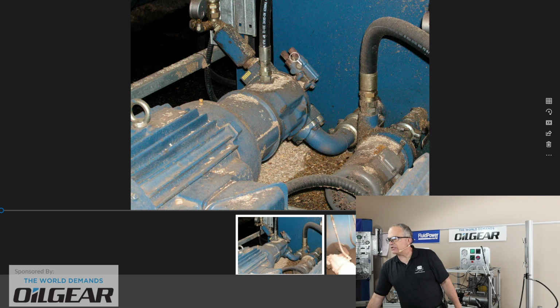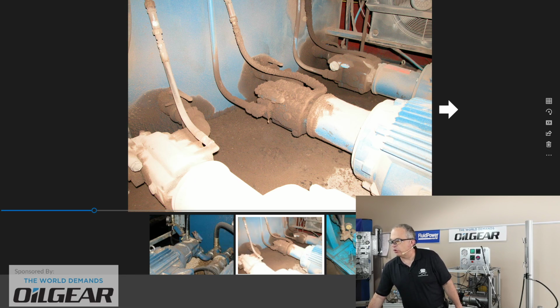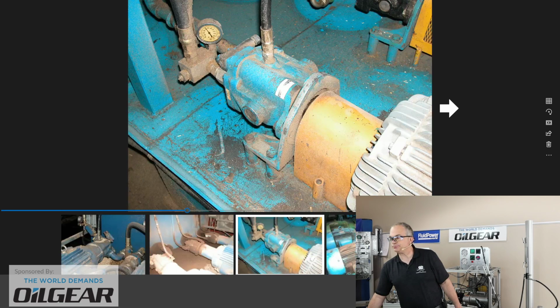And of course, if that second controller out from the pump body has no control hose hooked up to it, an external control hose that would come back, then in all likelihood you've only got the single adjustment of pressure compensate. And this one here, often the load sense, or sometimes referred to as flow compensator, has been tightened right down and knocked out of the control scheme, and there's only a pressure compensator. Uh-oh, I think there's a pump controller under there somewhere. Some pumps get a little bit dirty in operating environments.